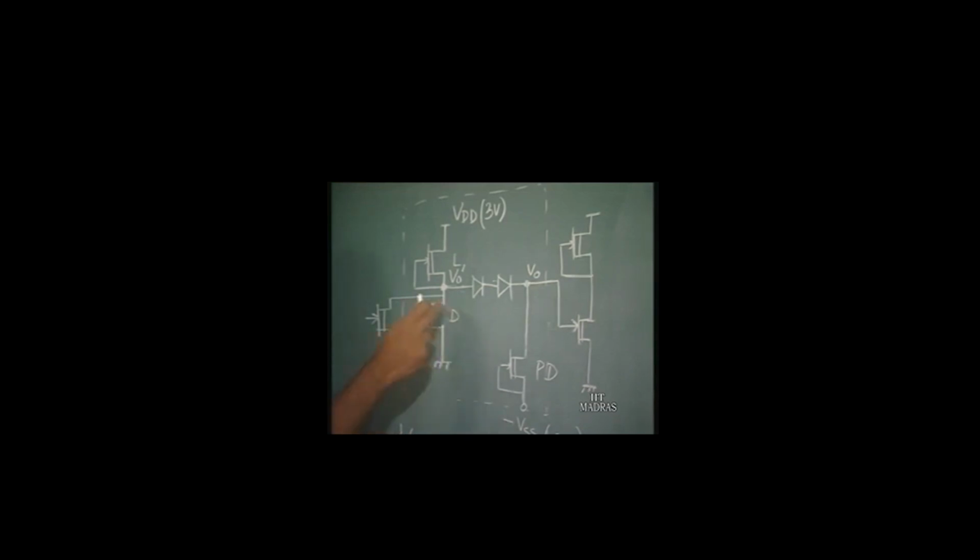Okay. What happens is, in this case, when this turns on, this output goes high, the pull down action takes place. So this input here goes quite low, and the pull down is going to be taken care of mostly by this pull down transistor.